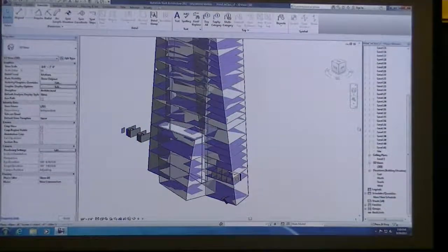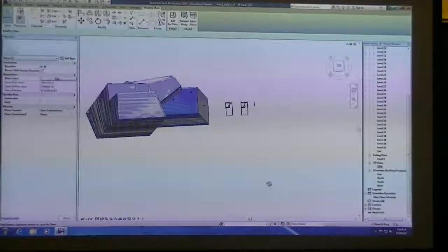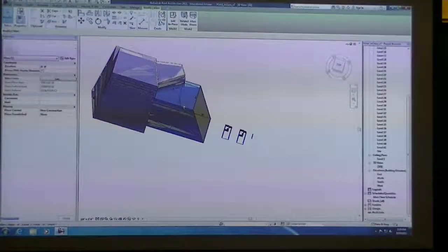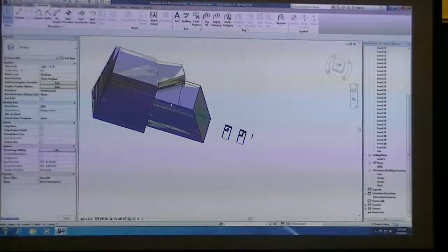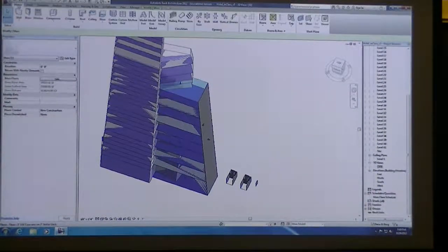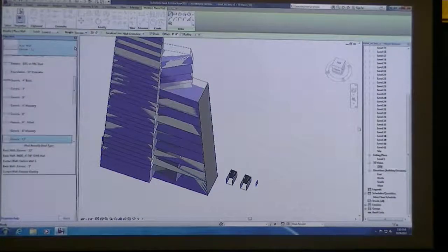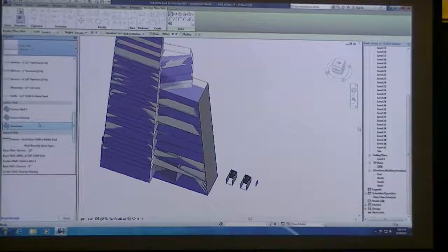The first method would be if you have a wall that is straight somewhere, and I think I have one, we can place a curtain wall by clicking on Home, choose Wall, and under Properties, scroll all the way down, and you should see, remember, we've just got our basic walls that we've worked with so far. You have other options down here called curtain wall and storefront.